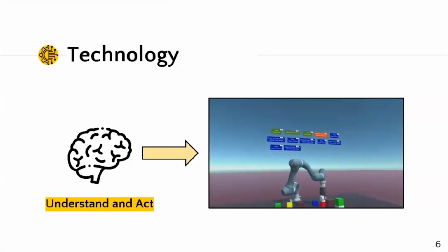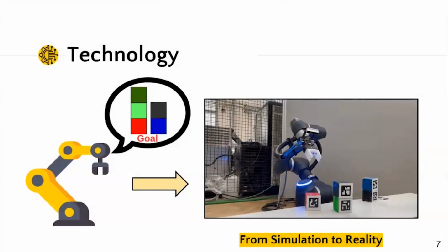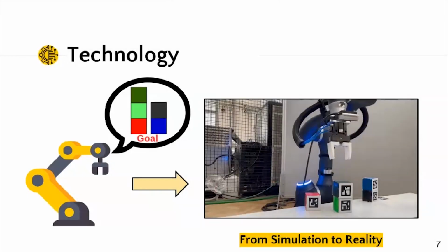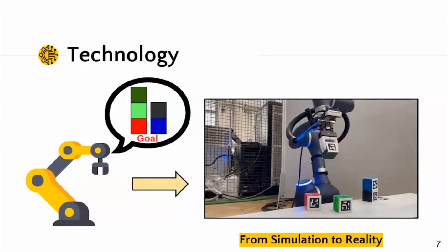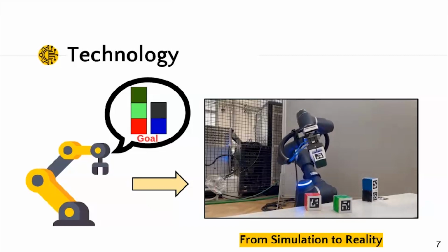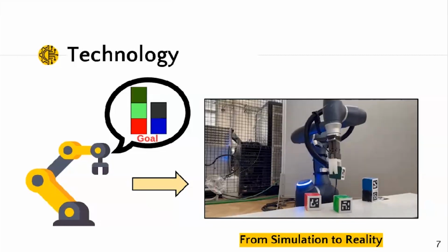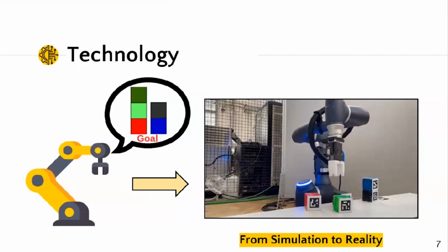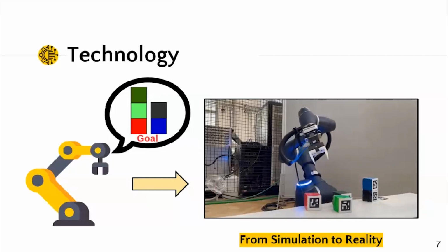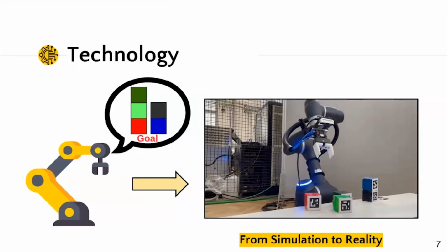The code is immediately transferred to the real robot, which understands the scene, and depending on the environment, it schedules the actions learned in the virtual environment and reproduces and uses the actual skill that it has learned to get to a final goal. In this case, two piles of blocks. And the initial condition could be whatever. And so the robot here is autonomous and guarantees flexibility.